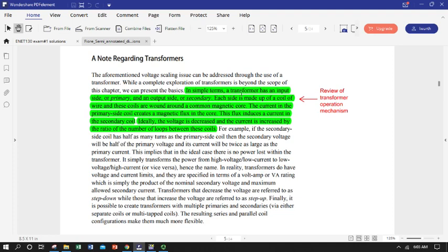that's probably coming from the grid. So if you remember back to your studies in AC, a transformer is an electromagnetic device. So we're using a magnetic field contained within something with a high magnetic permeability, like a silicon iron core, to basically convert electrical energy into magnetic and then back to electrical. So we have basically two inductors, at least in a transformer. One is our primary excitation, and it's coupled to a second inductor with that magnetic field, and that secondary is what we're using to supply our diode rectifiers.